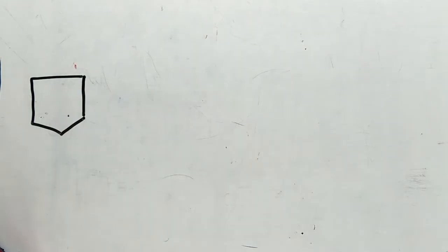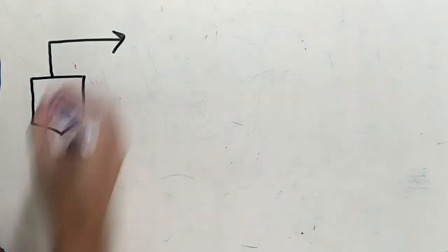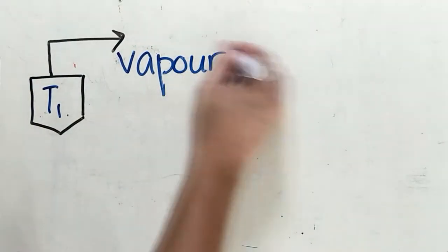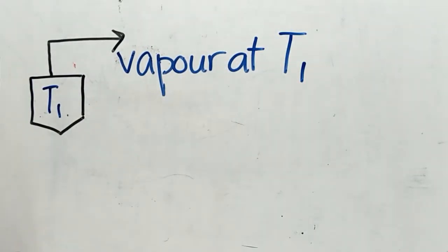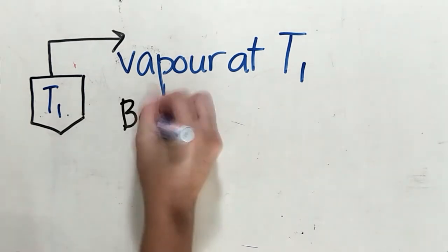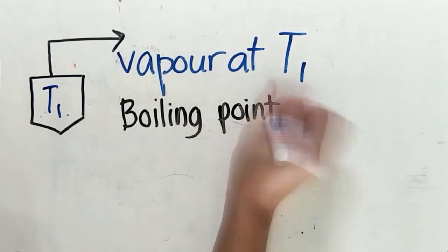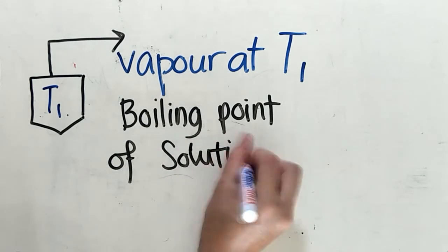The diluted orange juice inside the evaporator boils at a temperature T1, which is the temperature of the solution at boiling point. The boiling point of the solution is proportional to the pressure inside the evaporator. The higher the pressure, the higher the boiling point will be.